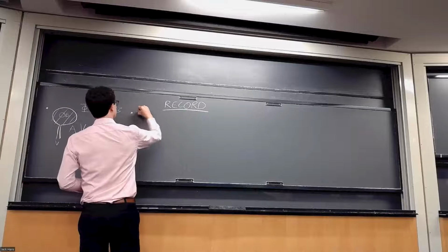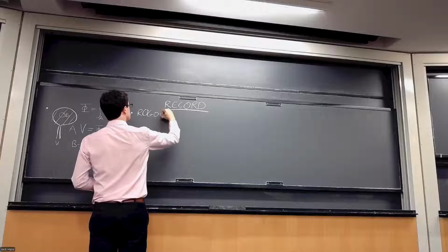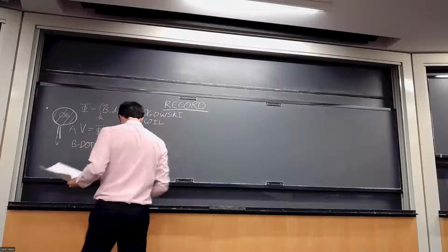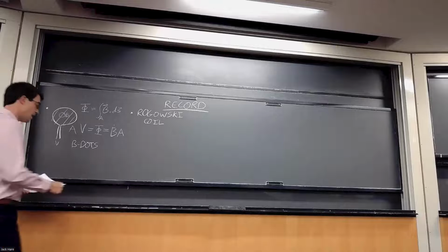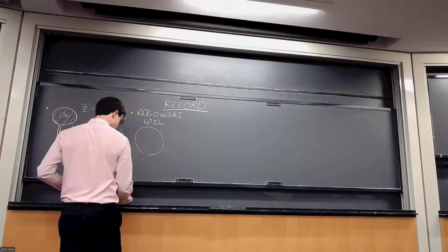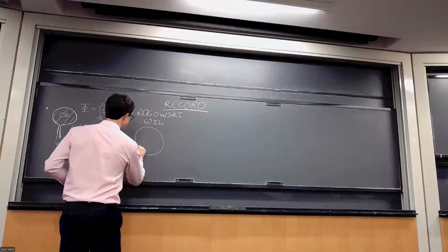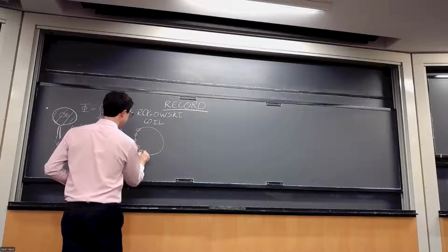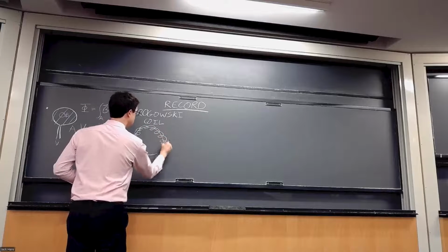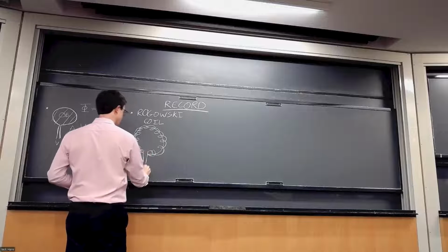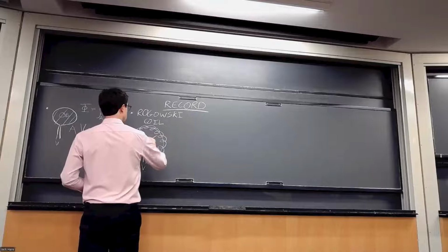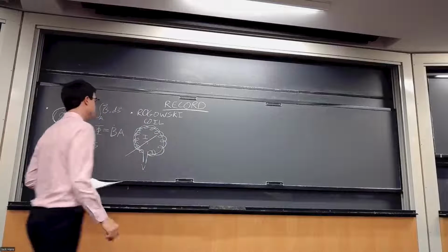We also talked about Rogowski coils, which is effectively a set of B dots arranged around the circle. So we have our circle like this, but now we have a load of B dots arranged all the way around, and we join them all together. And we measure the voltage again here. And this tells us something about the current which is flowing through this loop here.